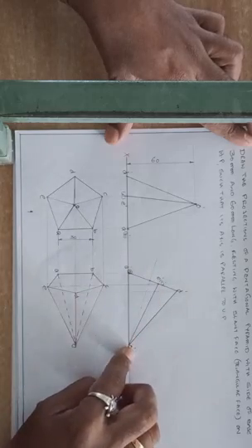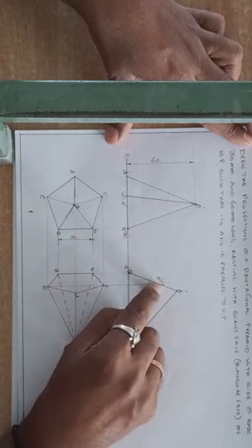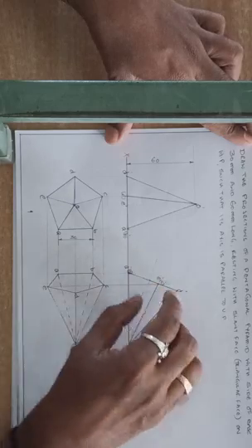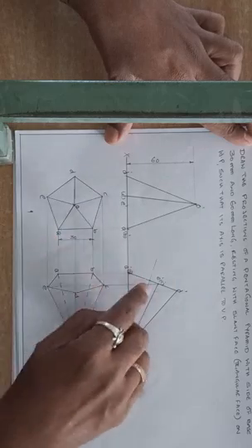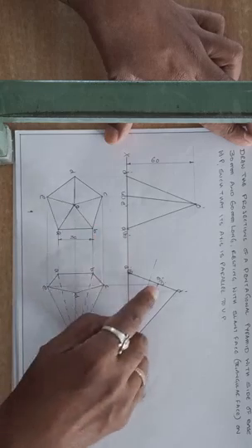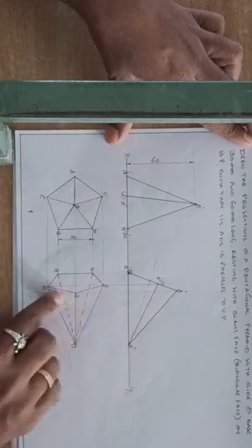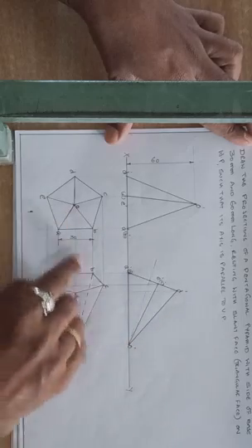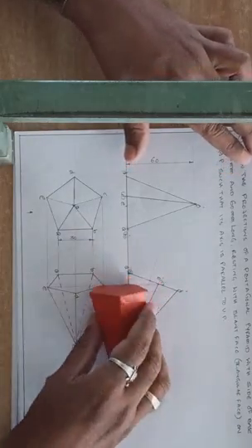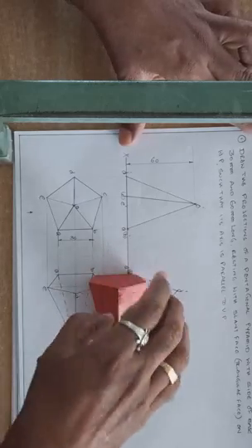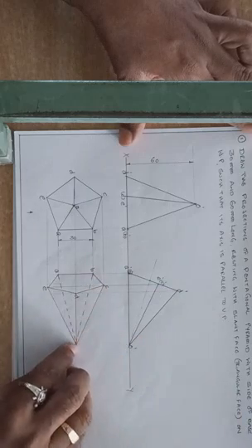So join with the O dash. Now transfer the notations here: A, B will be here, and C dash and E dash here, and D dash. Then projections downwards: from A downwards, horizontal; B downwards, B horizontal; C downwards, C horizontal. Then from D horizontal, from O also horizontal. Then looking from the top, if it is like this, from the top you can see the face. So make those points thick lines, then join with the O.